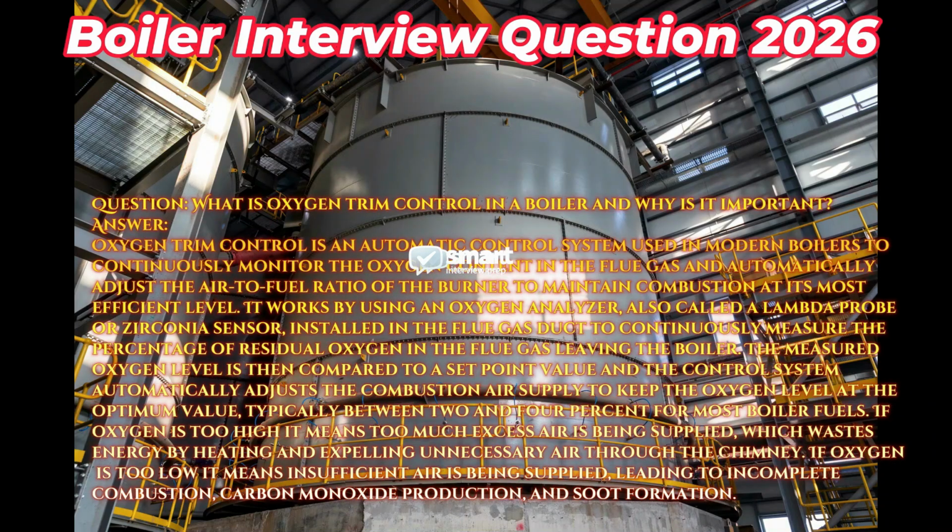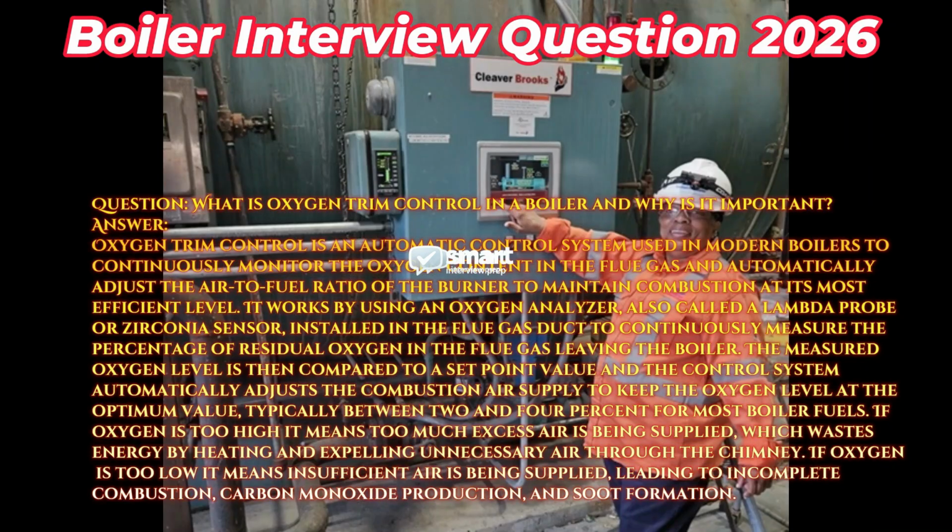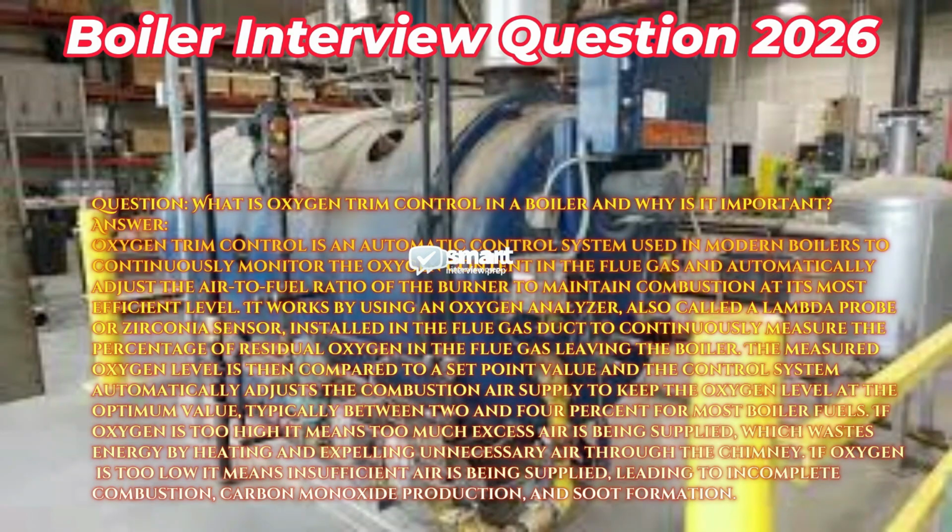Question: what is oxygen trim control in a boiler and why is it important? Answer: oxygen trim control is an automatic control system used in modern boilers to continuously monitor the oxygen content in the flue gas and automatically adjust the air-to-fuel ratio of the burner to maintain combustion at its most efficient level.